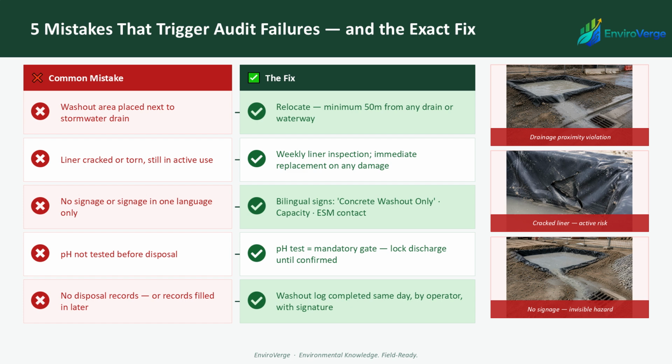Mistake 4. pH not tested before disposal. This is not just a documentation gap, it is a process failure. The fix? The discharge valve stays locked until a pH reading has been recorded and signed off in the monitoring log. If there is no valve, install one.